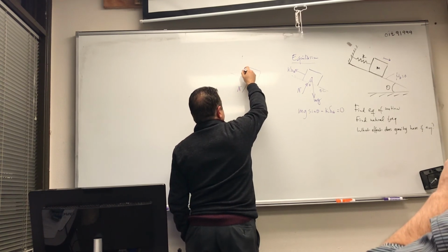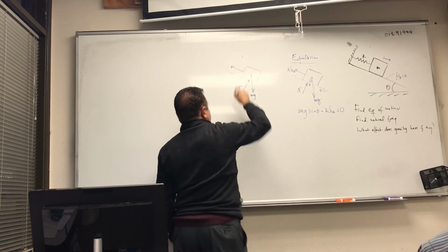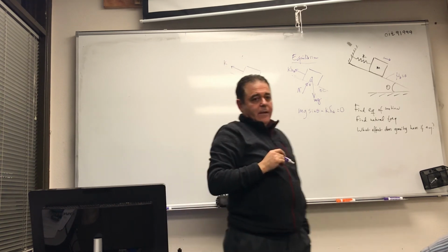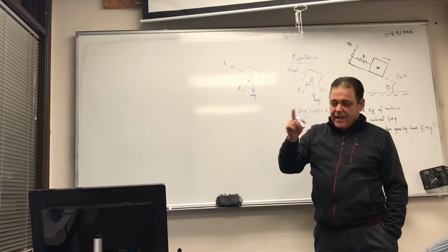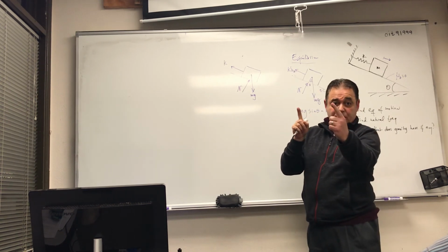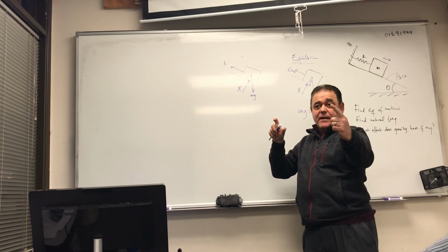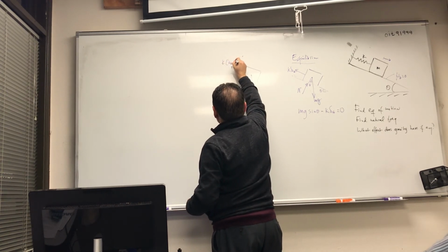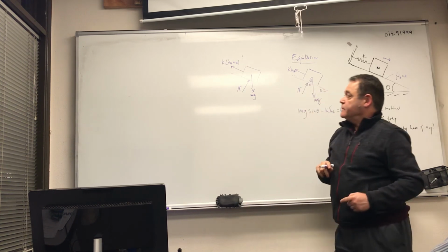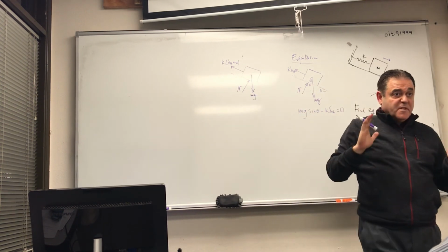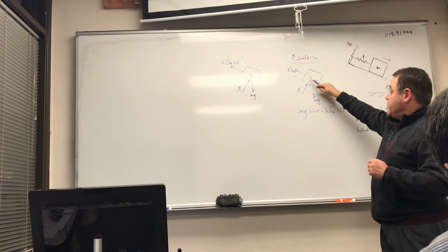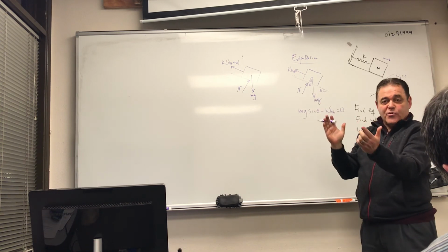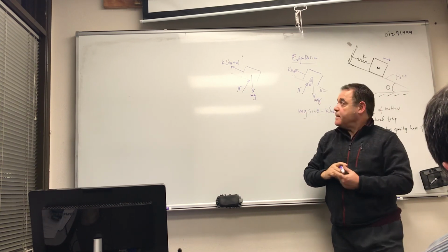A normal force, but how about this force now? What is it equal to? K times delta static plus X. I mean, it's already stretched delta static, right, and I'm pulling it an extra X. So it's gonna be k times delta static plus x. If you don't agree with this, please let me know, if it's ambiguous. The spring here is already stretched delta st, right, and I'm pulling it to the right by an additional x. That means the total stretch now is delta st plus x.